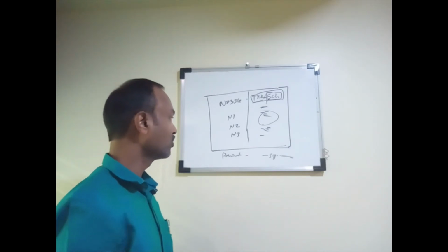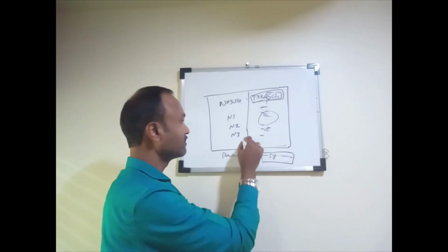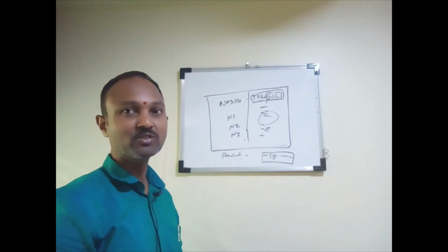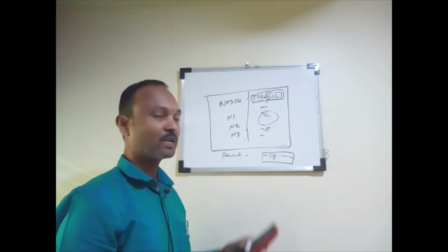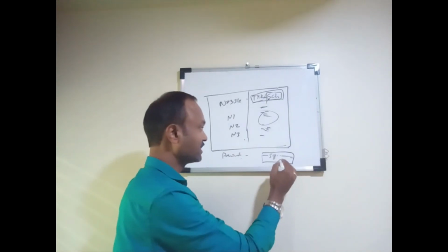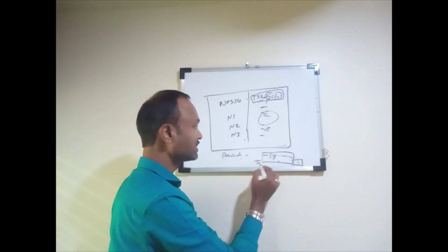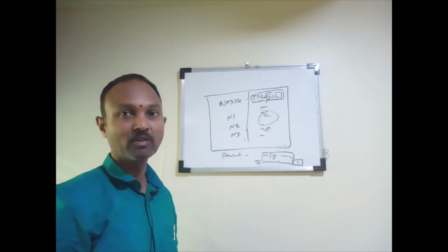So better if we go to this spec and take the clause which is applicable to this vessel. This is normally based on the temperature or material we are using. Accordingly we have to refer to that table in these specifications, and whatever the table mentions we have to indicate here as the painting requirement for this vessel.